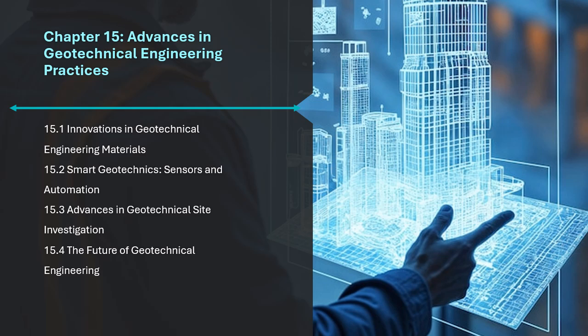Cone penetration test, CPT. This test involves the use of a cone-shaped penetrometer that is pushed into the soil at a constant rate. The resistance encountered by the cone is measured and used to determine soil properties, including stratigraphy, density, and strength.